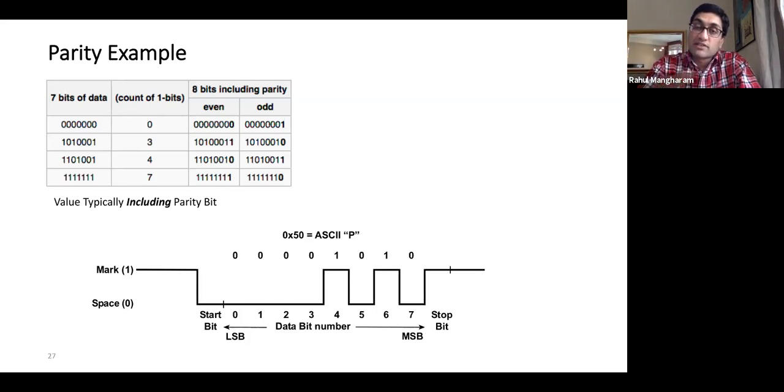With the CRC32, you would run this code, and it's a little bit more complex than just XORing, but it's a different type of sequence of XORing which bits. Then you check: based on the packet I received, I compute a CRC, and based on the packet you sent, you also send me a CRC with that. So I check, is my CRC that I computed on the received bytes the same as the CRC that you sent me? And then I say, okay, that's good.